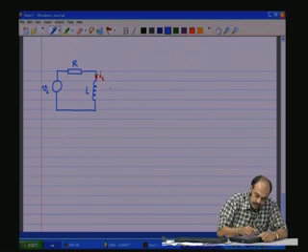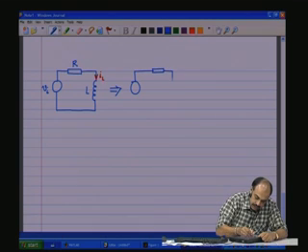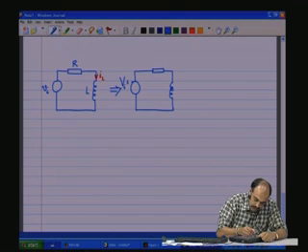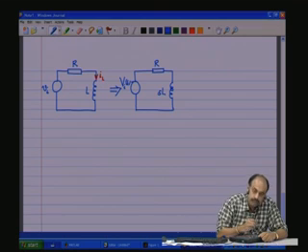Now, this we take it to the Laplace domain, the circuit, by a simple process of replacing j omega in the inductive reactance with S, and then we also capitalize all the variables and they become functions of S. This is R, and then you have L, and now the reactance would be SL.